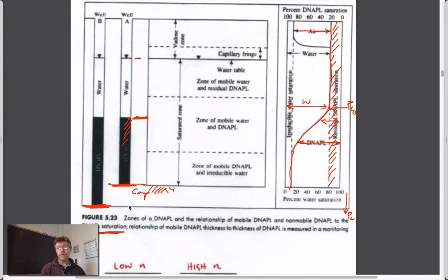And so, because you have 10 meters versus 8 meters of this stuff, it doesn't mean that in the aquifer it would actually be 10 meters deep, for the reason that we stated. And so, in the same way that free product that floats on the top is a bit of an anomaly, because the true thickness of that is not what you necessarily measure in the borehole, it is actually less than that. For DNAPLs, it's the opposite case.